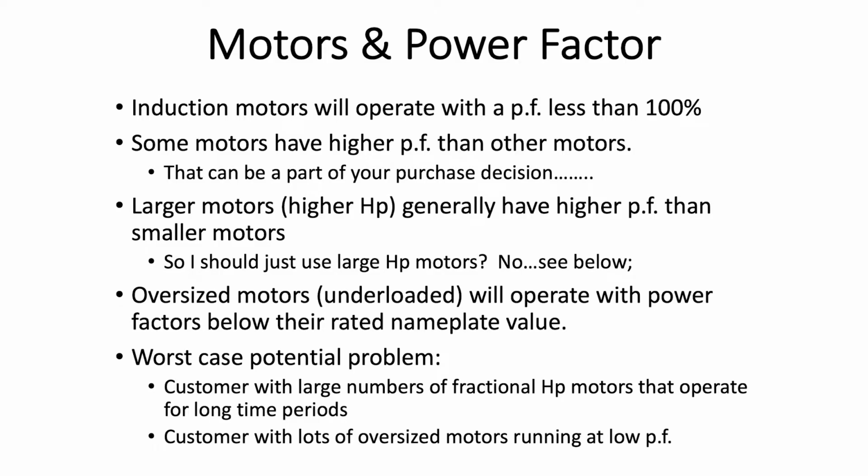So motors, induction motors operate with a power factor less than 100%. Some motors have higher power factor than others. That can be a part of your purchase decision. Somebody asked yesterday, well, how do you know what the power factor of a motor is before you buy it? There are databases and other things, online programs you can go, and you can basically look and say, for a 100 horsepower, 3-phase, 460 volt motor, what's the range of all the power factors for all motors I could buy in the market? So if you can go to a database and look up and see what the motor power factors are, and what the high and the low and the typical range is, you have a better idea of what's good and what's not so good.